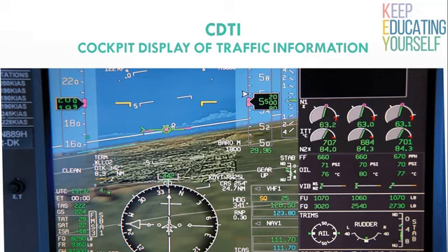Direct air-to-air transmissions of ADS-B messages support display of proximity aircraft on a CDTI. In addition to traffic based on ADS-B reports, a CDTI function might also display current weather conditions, terrain, airspace structure, obstructions, detailed airport maps, and other information relevant to the particular phase of flight.